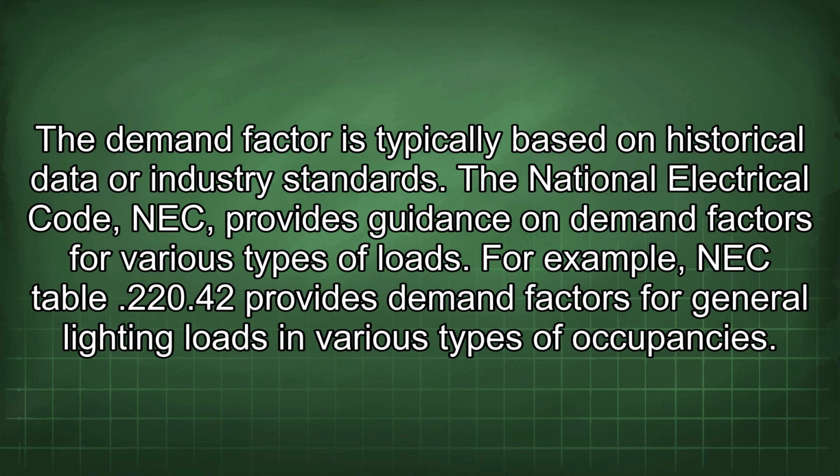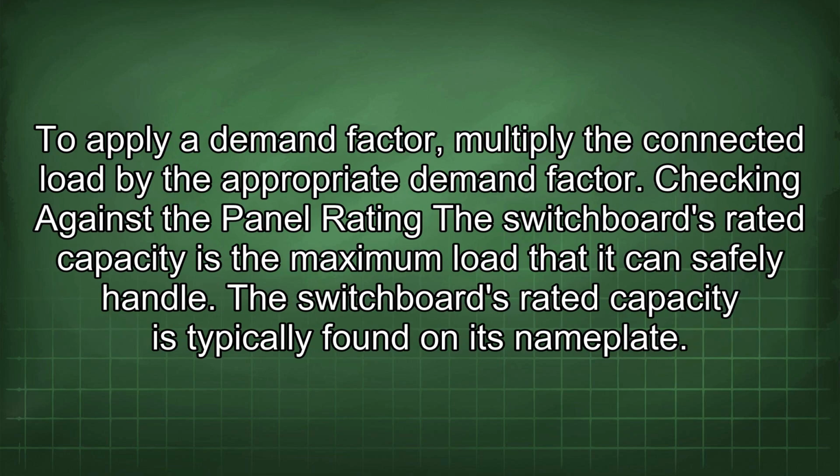The National Electrical Code, NEC, provides guidance on demand factors for various types of loads. For example, NEC Table 220.42 provides demand factors for general lighting loads and various types of occupancies. To apply a demand factor, multiply the connected load by the appropriate demand factor.